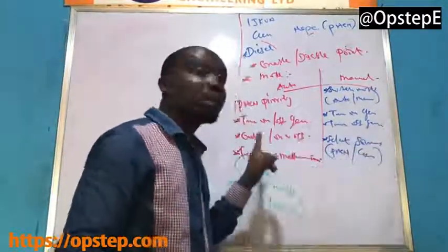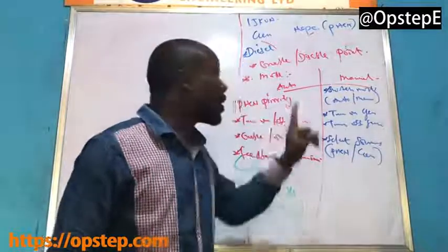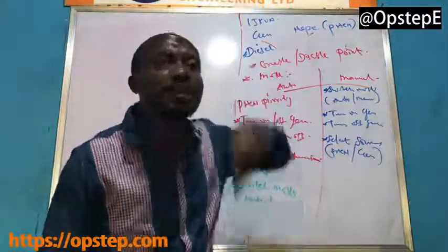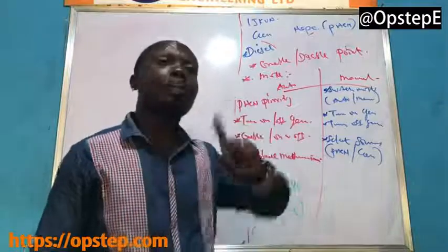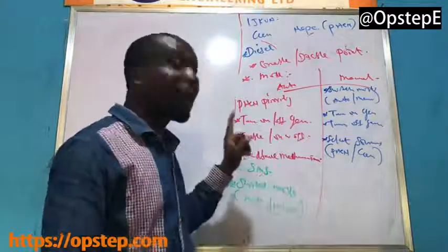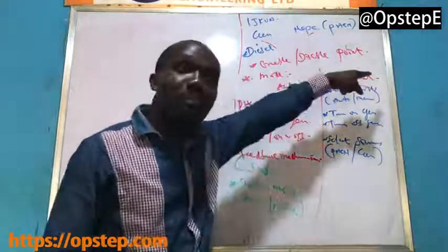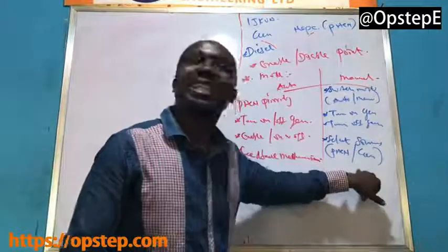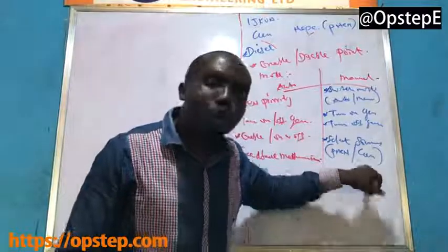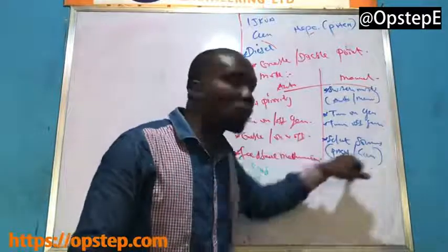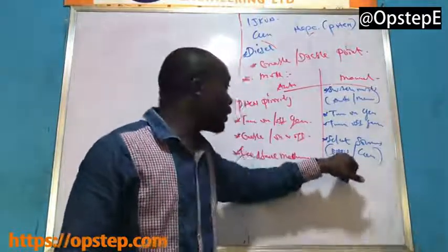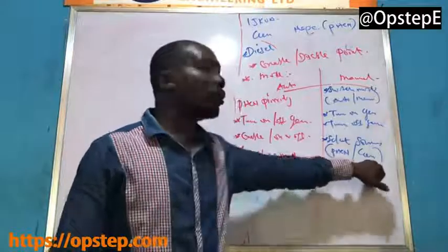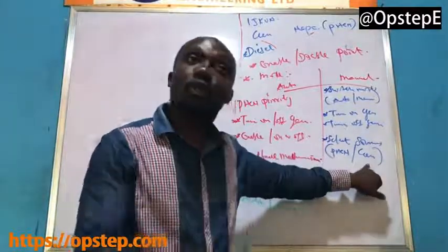In auto mode, NEPA is prioritized. If NEPA is not available, generator becomes the next priority. While on generator, if NEPA comes on, it turns off the generator and does what? And goes back to NEPA being the priority. Do you get it now? But in the manual mode, it doesn't select that for you. You are the one that decides which of the sources you want. Is it the NEPA source or the generator source? That becomes your responsibility.